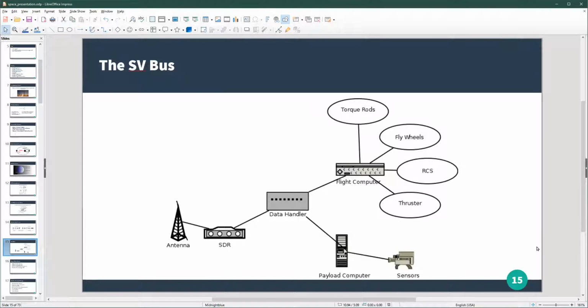And that's one of the things you can do right away if you get an SDR dongle, a USB software-defined radio dongle: tune into your favorite FM radio stations right on your computer. Most SDRs are USB dongles. I am coming around to the idea that the best SDRs are actually Ethernet based, for reasons we'll get into later. But the cheap ones you can get for like 20 bucks. USB ones are fantastic. And like I said, we're going to go over this a lot because SDRs are everywhere in space vehicles and ground stations.